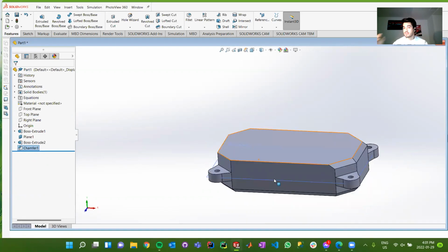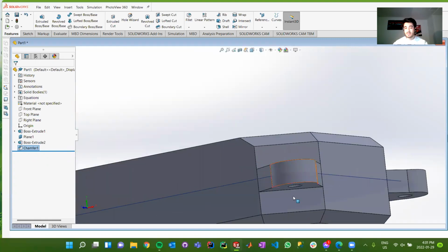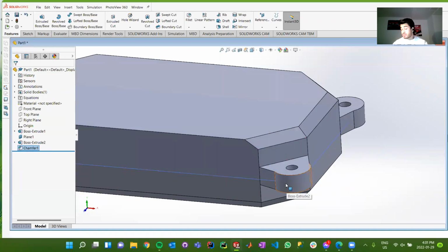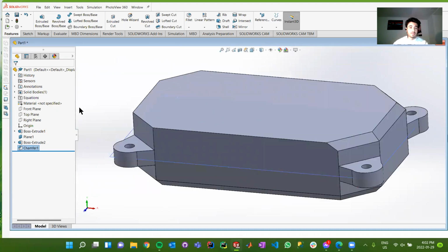or a little bit more like something that you'll see packaged. These little edges right here on the tops of the bracket, as well as the bottom as well, those are potential areas for stress concentrations and could be difficult for manufacturing. But we're just going to simplify it for now. We're going to ignore those just for the sake of actually attaching our arms. And this is what you see being done in a lot of different small toys as well.